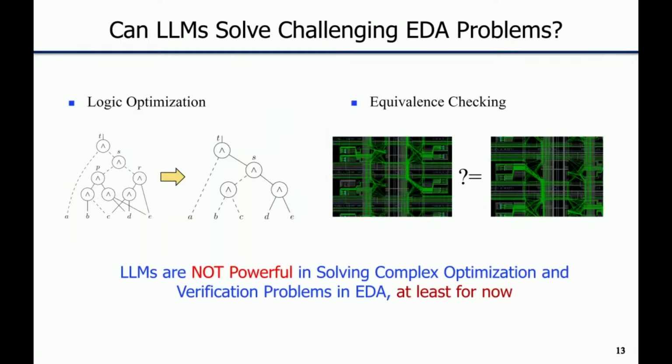I'm thinking that on the left side you have probably a binary decision diagram for logic synthesis, the logical optimization. And basically it has a canonical form. At the end of the day, you can bring all the circuits into canonical BDD form, and then you can have a very classical traversal of it and code it as a prompt for training.